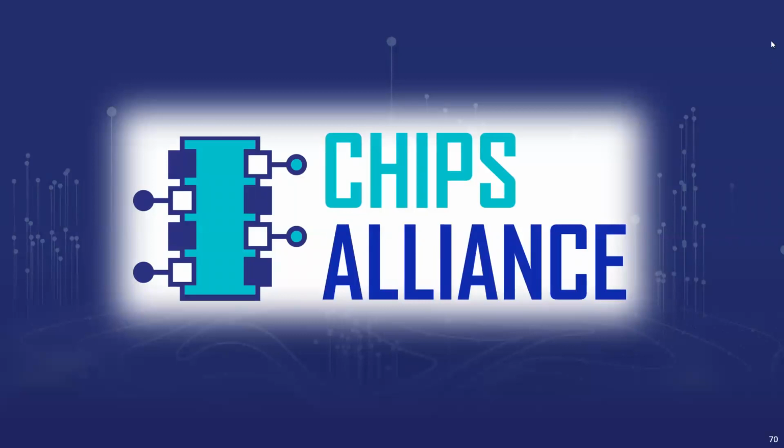But if you're moving forward to 2.5D or even 3D, right? For 2.5D, I believe most of the foundries today already have the capability to enable micro bump pitch, and we should be able to scale the bump plan based on the pitch size available for that process technology, right? And 3D will be more geared towards the process node that is being enabled as the base die for the 3D.